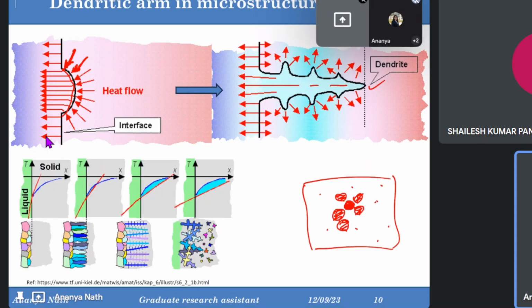For high cooling rate, the things go in the reverse way. The delta GV in this case is more and R star is less, and even for a less R star value the grains are stable. So you cannot relate these things with a super high cooling rate, because for high cooling rate the things are going the reverse way.